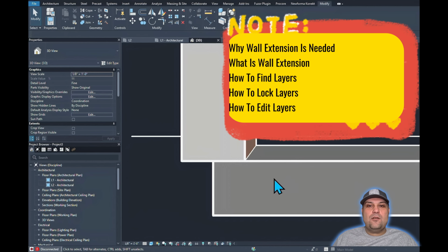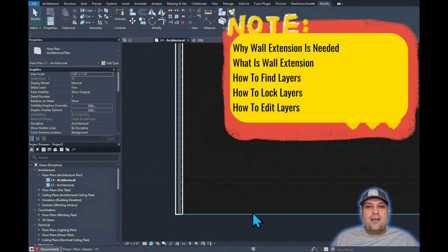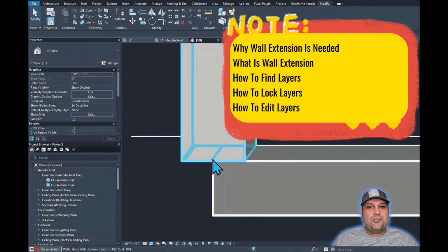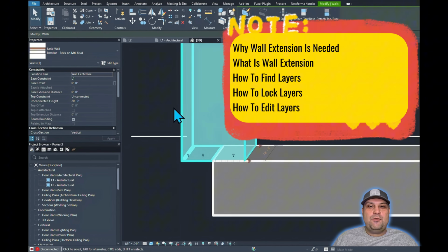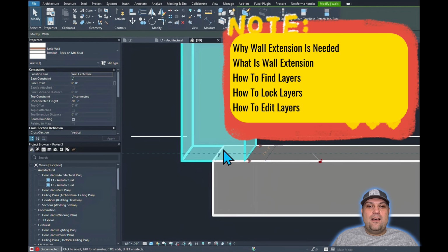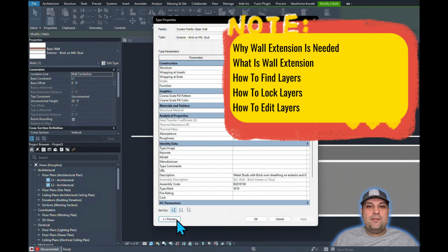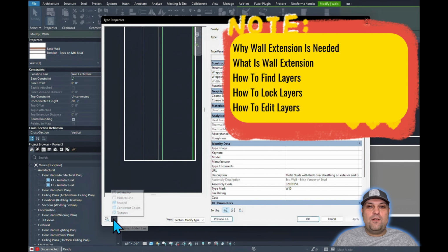In today's episode, Learning Revit, I want to talk about a very important topic. I've received a bunch of Revit models when I export NWCs and I look at everything in Revit. I see the perimeter walls or exterior walls are not as realistic as possible. It means half of the wall is on top of the slab edge and half of them are floating.